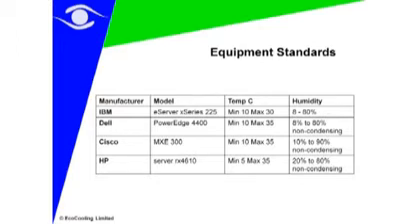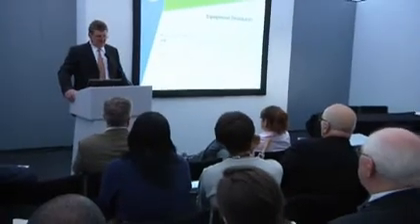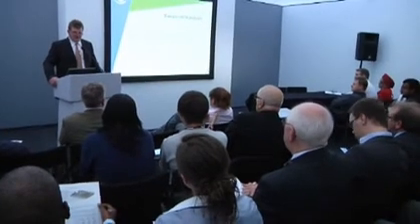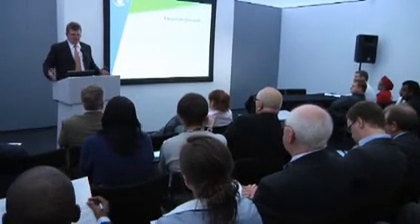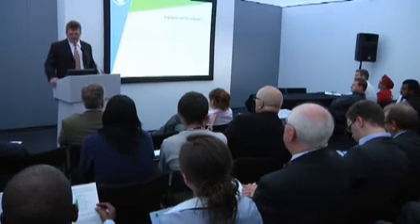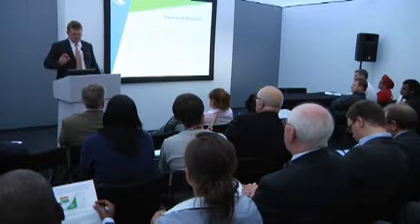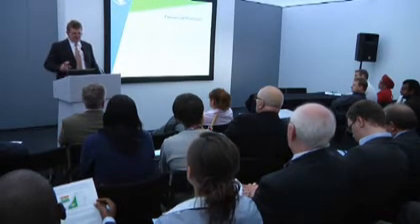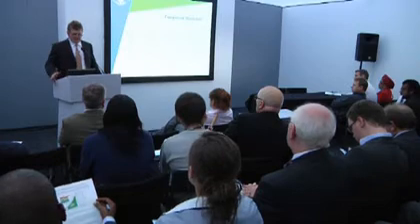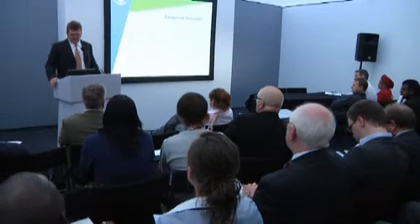So let's look at a few standards. You would expect IBM to have some fairly rigorous standards. You take a standard server from them and suddenly you see that the temperature spec is 10 to 30 degrees centigrade with relative humidities 8 to 80%. When people look at their equipment, most of them have never been given the environmental operating specifications, and that's a surprise to most people. That's the key reason why we can start using a radically different form of cooling for modern equipment.